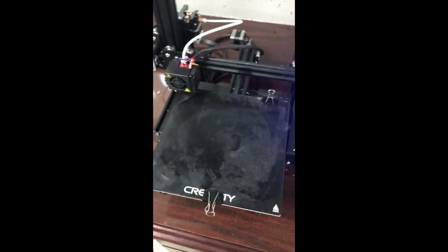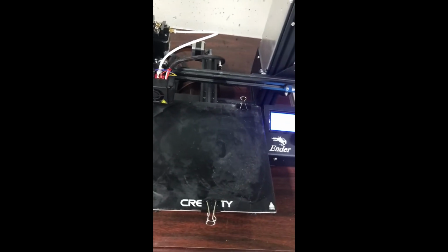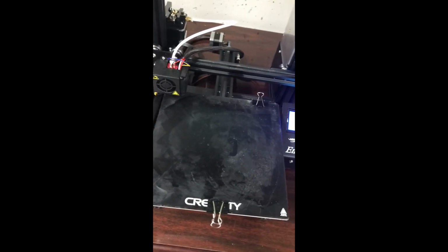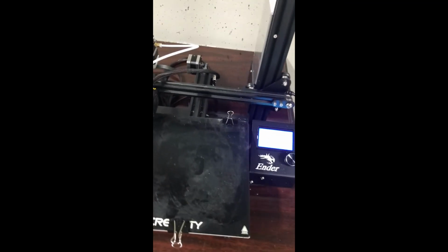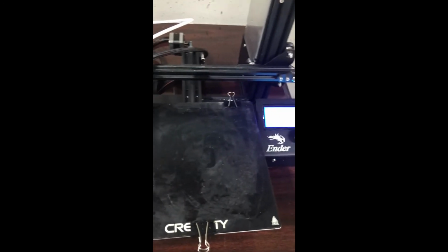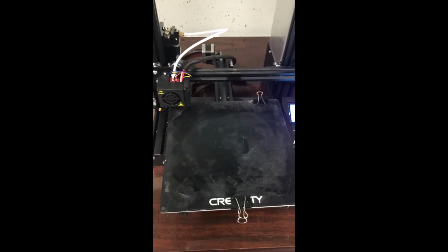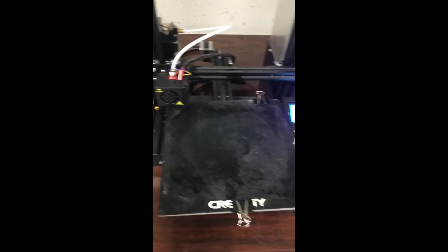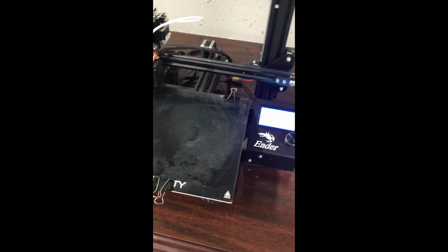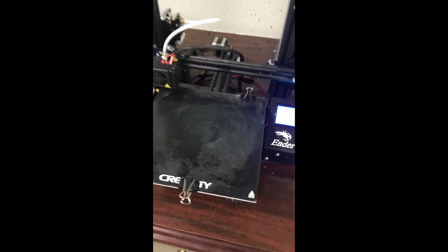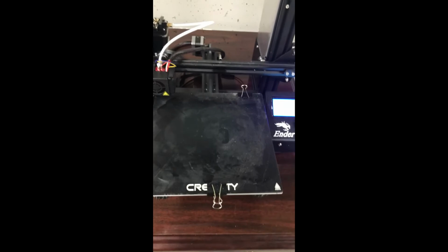Another option, which tends to be better, is you can go to sites such as Thingiverse and download test 3D prints, which go ahead and do a print all across the build plate. You can test how level it is by looking at the result of the print, and you can do it really quickly. The prints aren't that long, so you can go ahead and set it up. If there's any problems, fix it, and then you can go ahead and do another print and test it out.